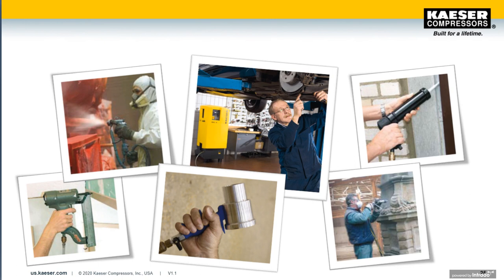Most of the compressed air demands shown here are straightforward: painting, air tools, caulking, stapling. It's a manual tool or device that has a manufacturer's rating for pressure, flow, and air quality, so it's pretty easy to identify those during your walkthrough. What makes them targets is the way they're being used, with mostly flexible hose lines that come with small fittings, filters, and regulators.